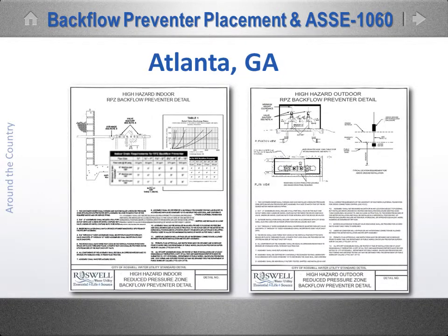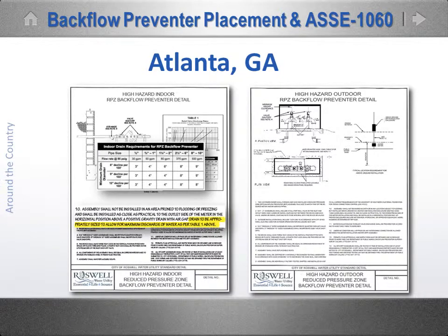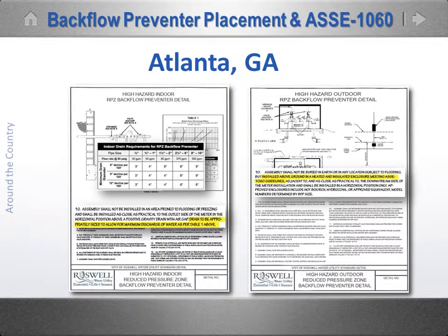The drawings for the indoor method explicitly address drain system requirements and force designers to reconcile the flood rate risks with specific drainage system capacities. And the outdoor method mandates an enclosure that is ASSE 1060 compliant.